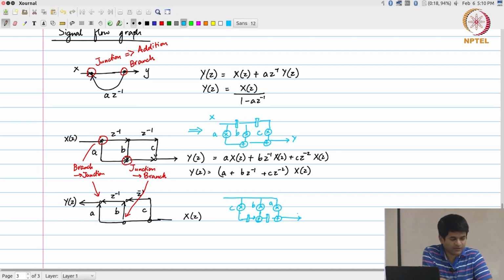The important point, the one that ultimately becomes relevant from a hardware point of view, can be seen in the context of something that we will be looking at in a bit more detail later, but you already know it. It's something called the critical path of the circuit. Okay. So what is the critical path in a digital circuit? It's basically the longest combinational logic path through a circuit. Okay. And in this case, if we look at it, the longest combinational path is essentially going to be like this, right? The multiplier followed by two adders.